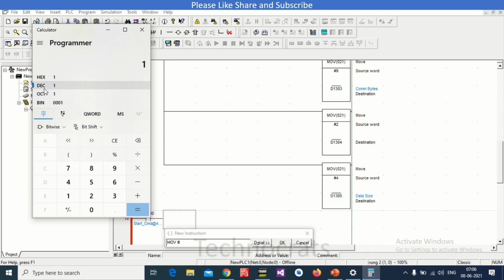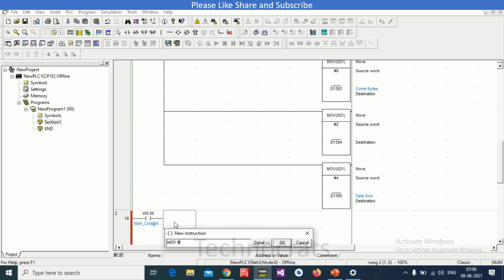Now we also have to write the frequency. I am using 40 Hz, so that will be 40.00, and the hex code is FA0. FA0 is the hex code. So I will write here #01 is your start command for the drive.